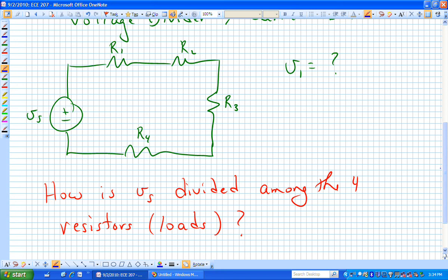What's an unknown that would really help you answer some questions? The current, correct? If we knew the current, because everything is in series, the current's the same, we could then find the voltages that we might be interested in.